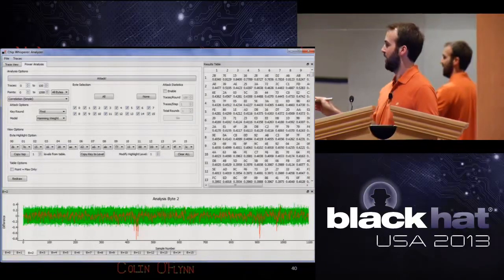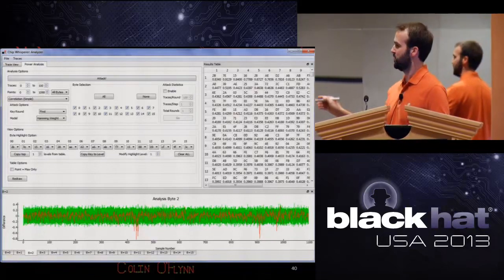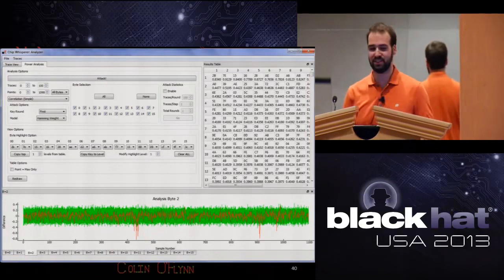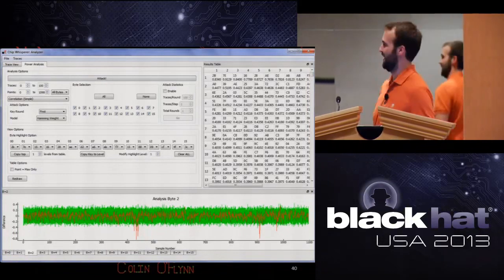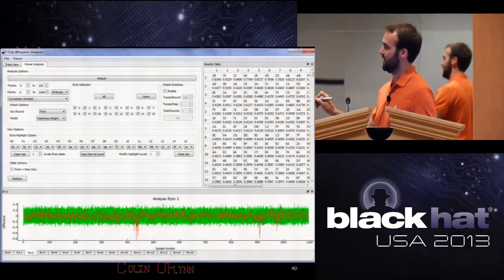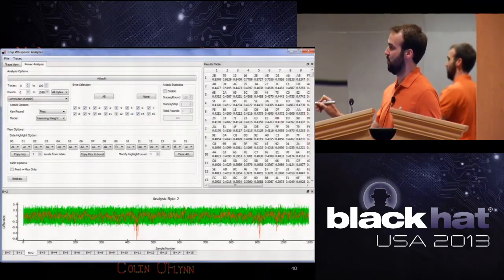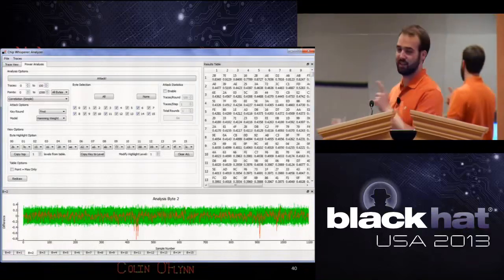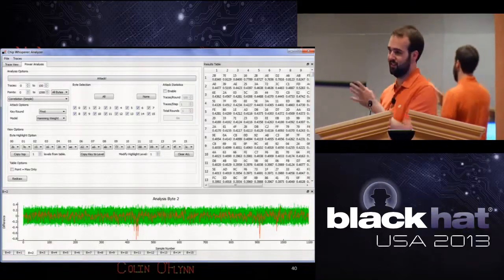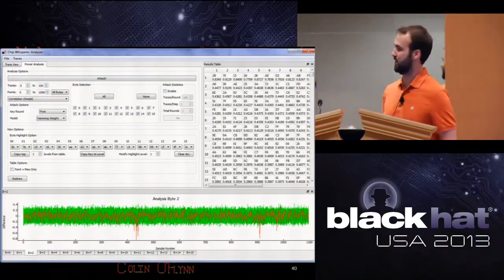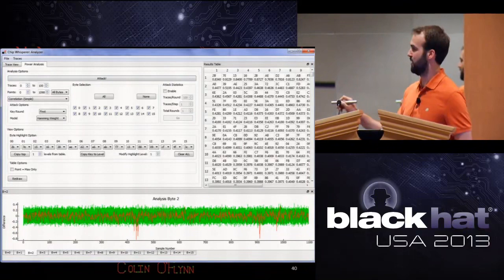So yeah, at this point, I don't know, the hardware works. Until recently, you couldn't do that with the hardware. I added that, but I haven't tested it well enough to do it live. You could say, well, I'm going to save time, and you literally only need one sample. If you could sample the right point, you just need a sample and hold system. You don't even need an ADC. But because you don't know the point, I just do all of them. And they occur at different times.